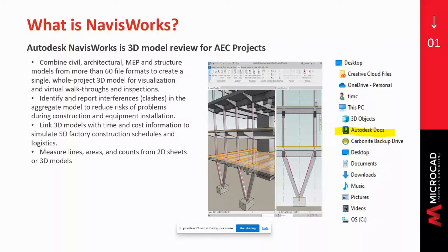So why do I want to clash detect? Well, let's say the architect designs the building and puts in the places where the elevators go, but then the MEP engineer comes in and designs a duct right through an elevator shaft. Well, the clash detection is going to find that for you, rather than one day the people doing the construction of the duct work calling to say, hey, man, the plans are showing me to put this right through this elevator shaft.